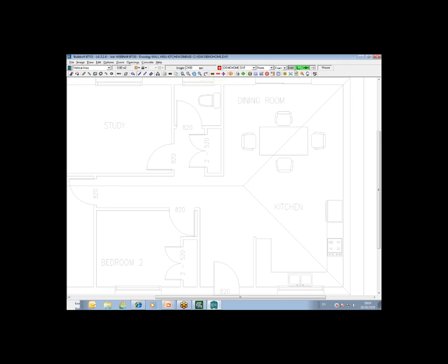So as before, what I'm going to do, before I do my takeoff, is turn on the dimensioning, so that as I draw the lines, I'll be getting a dim on each line. So this is again the ruler type icon with 1 in it. So I'll turn it on, it's depressed. I go to the first line.